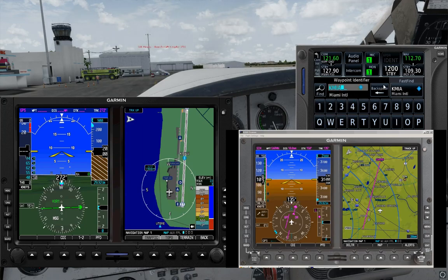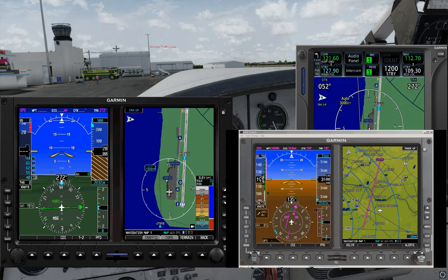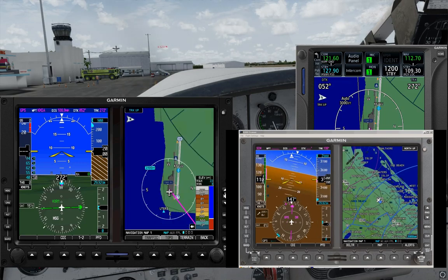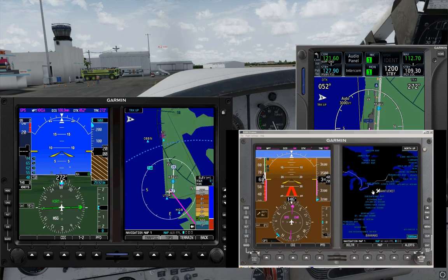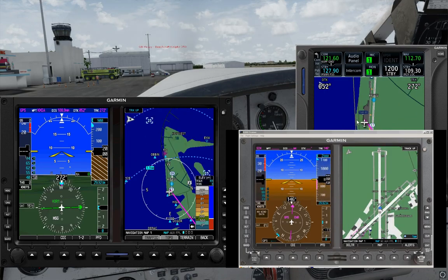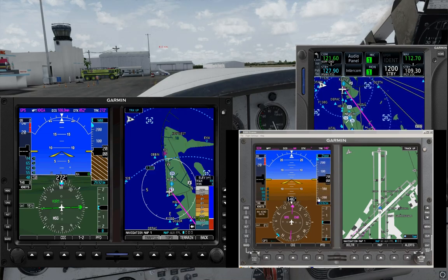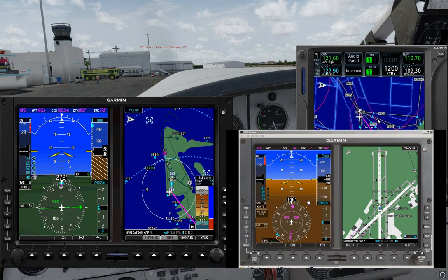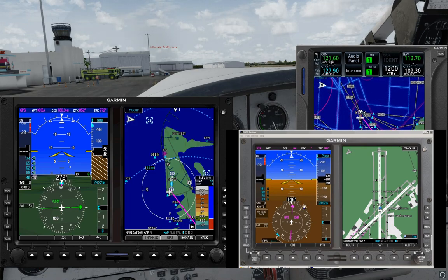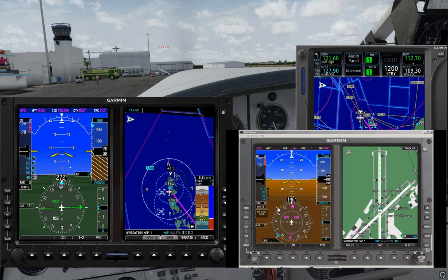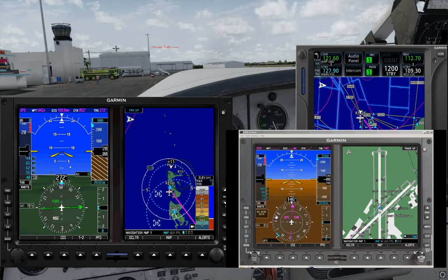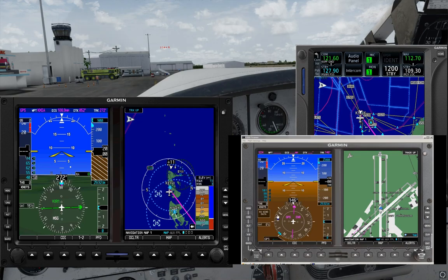In this case, I'll hit OK again. So basically what's happening is the system is locating us, geolocating us, and stabilizing any altitude or airspeed information that's in the system. So that's the basic power-up sequence for the Garmin 430, the Garmin GNS 500, and once the system is started, we'll start to look at an overview of the PFD and the MFD.